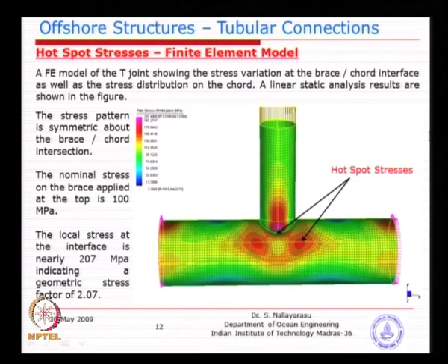So, you could see here on that particular location is very high stress of 200 plus, but the same 100 megapascal only I have applied at the top. Most part of it is green, basically there is no change, no deviation in the load, no change in the cross section, but when it comes to the connection at this point, it is reflected on two sides, reflected on the brace and reflected on the chord.